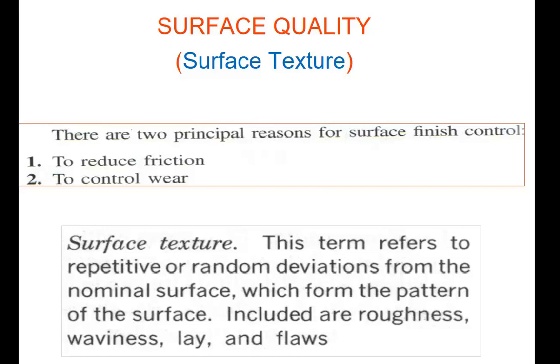To be able to increase the mechanical efficiency of the mechanism via decreasing the energy dissipation, we need to control the size of irregularities, knobs, protrusions over the surface. In doing this, we use the surface quality concept. The main parameter in controlling the surface texture, or using this definition, is the roughness value.